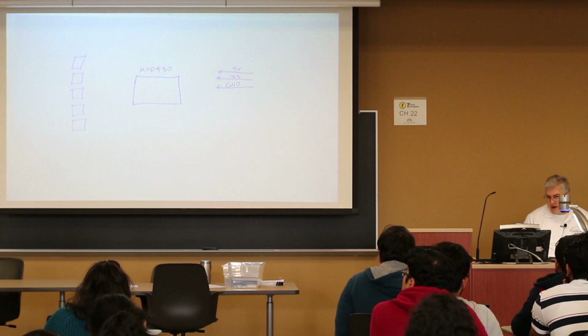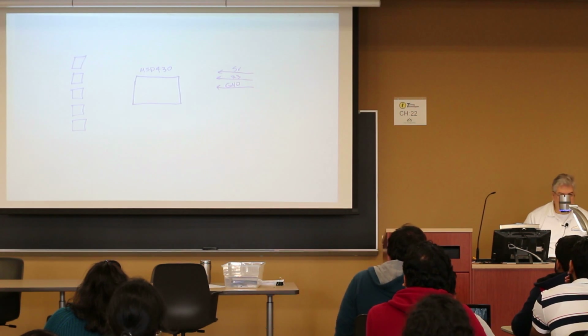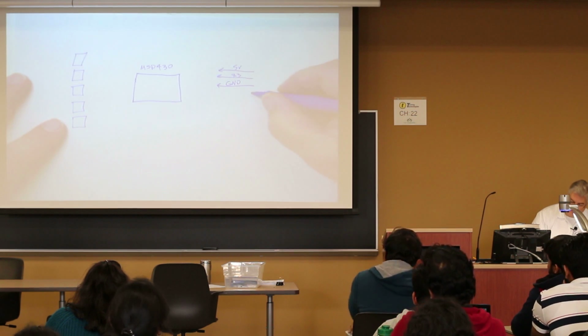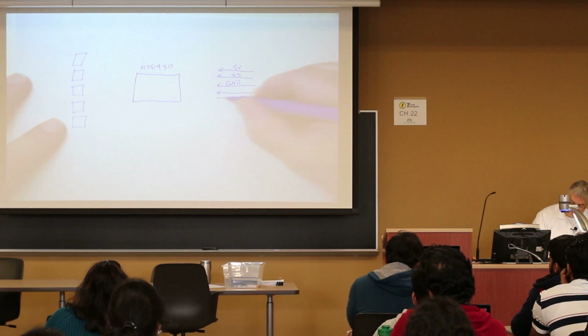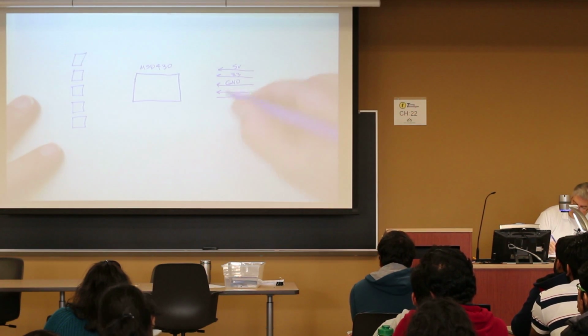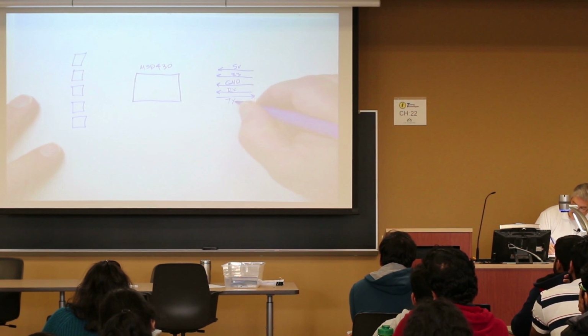What else do I have coming from that board over there? UART, all right? And UART implies RX and TX. And let's see, since it comes in here, that will be identified as RX for it, and this will be TX for this. All right?